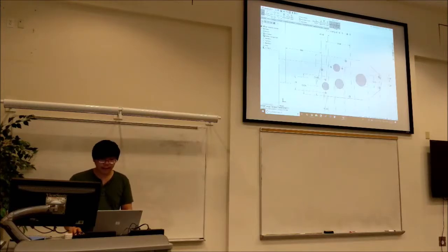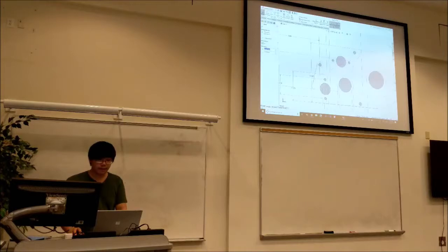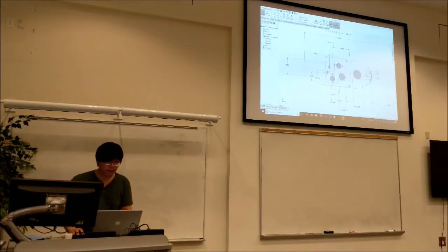And then for things like this, when it's blue in SolidWorks at least, or I think it's blue in Inventor as well, it just means that it's underdefined, right? So this is all the possible positions you can put your motor at. And it doesn't really matter, right? Because we defined it being tangent to this circle. So any of these positions work in terms of meshing the gears. So we can just put an arbitrary dimension in there to make sure the motor is fully defined in our sketch. So I'm just using a construction geometry line for us to dimension off of.